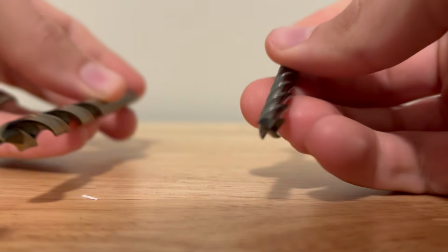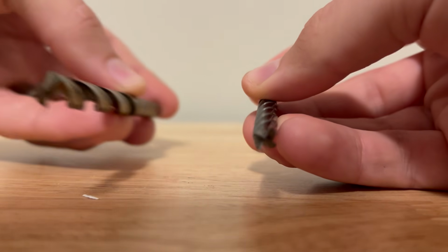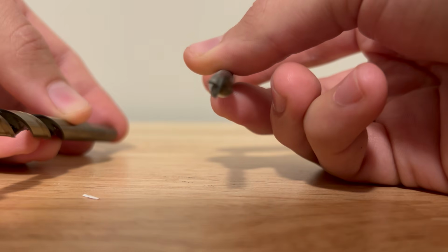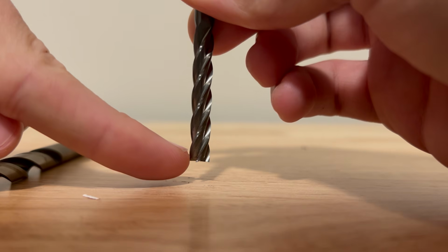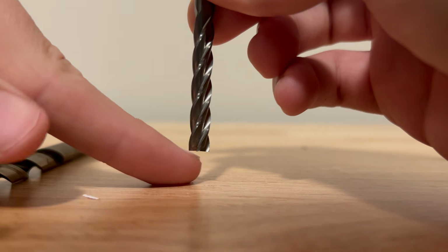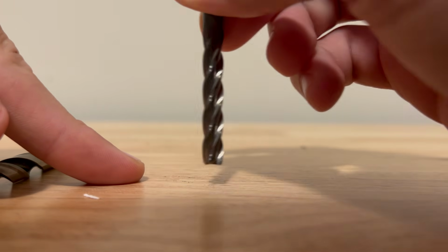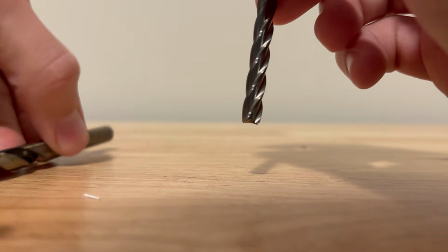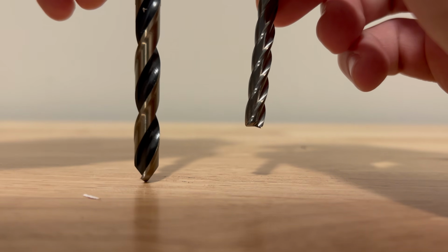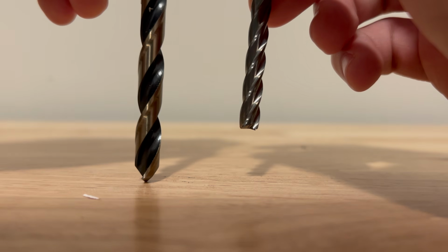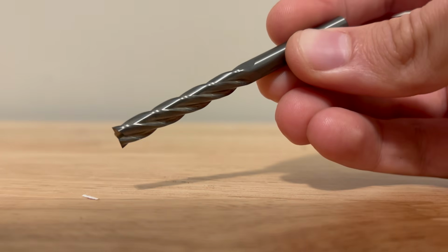And also with that, if you'll notice how much material is removed with the flutes on a drill, the end mill is much more solid by design because it's made to cut on the sides, with partial engagement and even full engagement on the cutting tip while it's moving. This is how you make slots, profiles, things like that, where a drill just makes a straight hole. This is the main difference in drilling and milling. And you bought a milling machine, so we're only going to focus on milling tools.